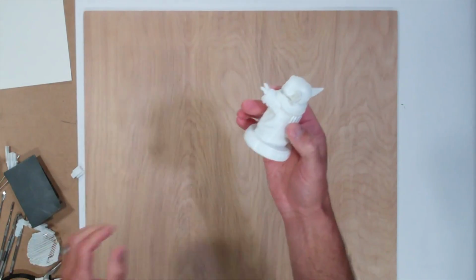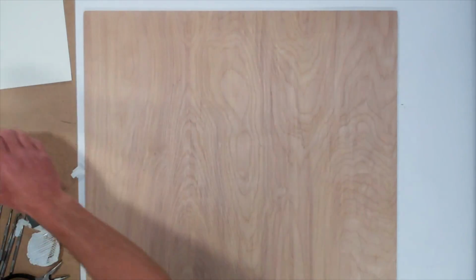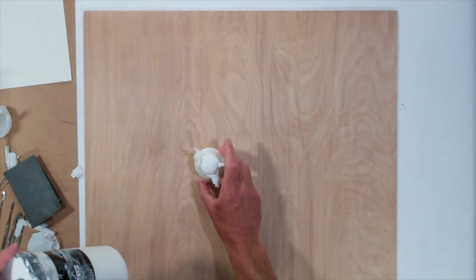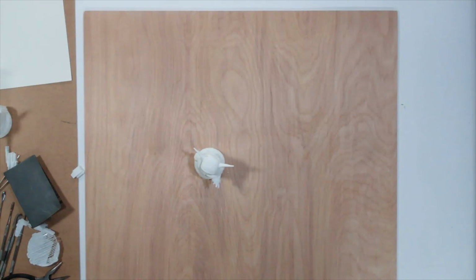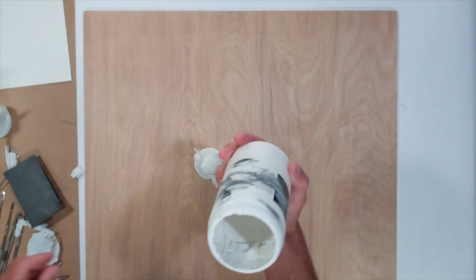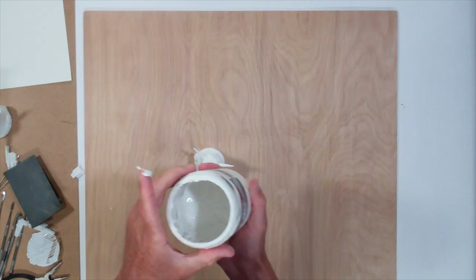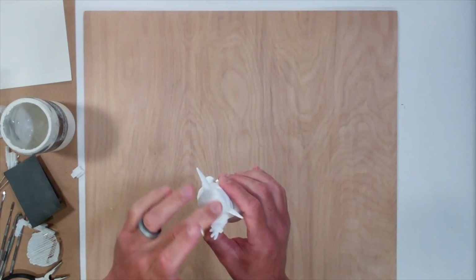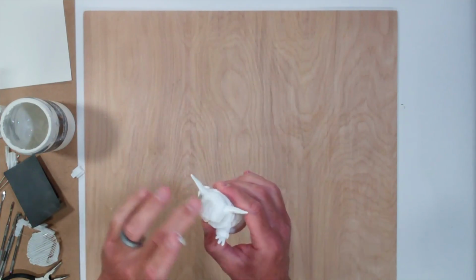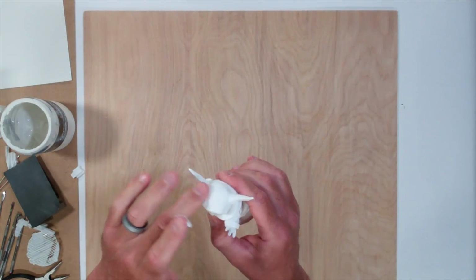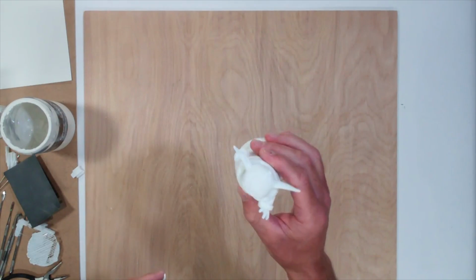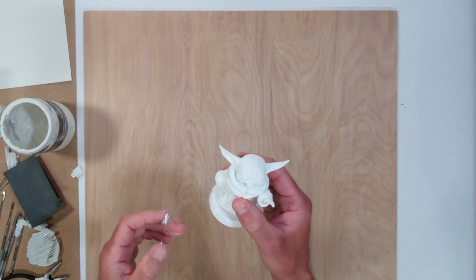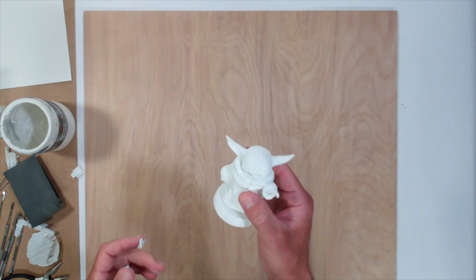The next step after you finish taking off the supports is to fix any little issues you may have with the print. This modeling paste works really well. It has the consistency of toothpaste. You can use your finger or a brush. I take a damp brush sometimes and go over top of the surface, or a damp finger, so you have less sanding to do once it dries. It takes about 24 hours to dry. It's thick enough too that you can actually glue pieces of models together with, and it holds really, really well.